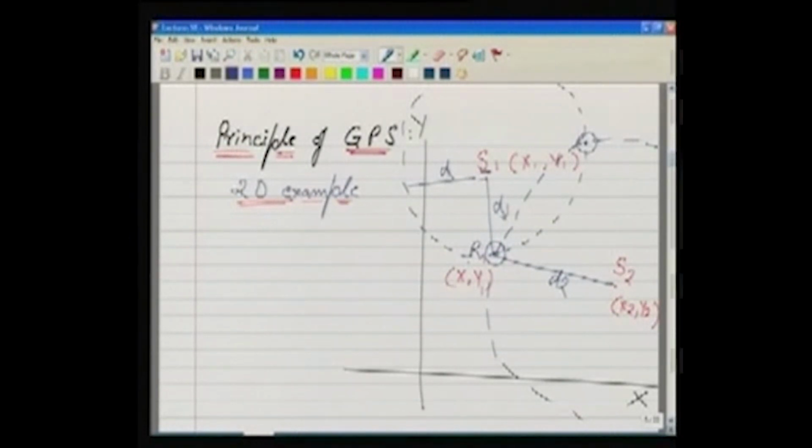In order to find the solution, if we know that one of these positions is not possible, then we can fix it. What we have done so far is try to understand, in 2D, one unknown point: to know its position, we measure the distance to two known points, and we end up with two positions.